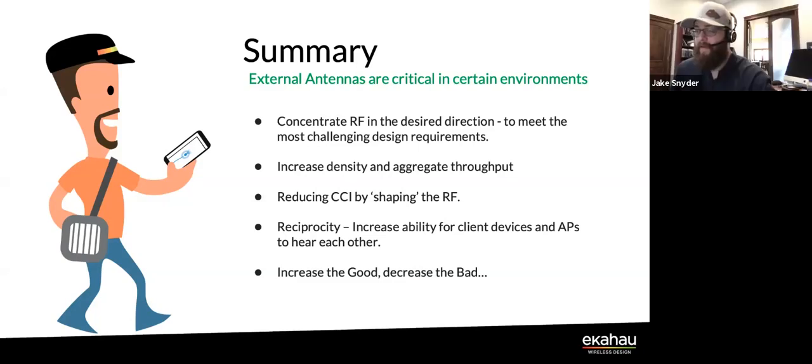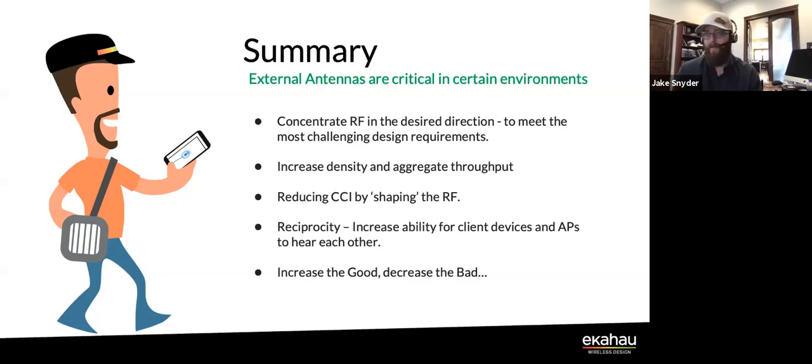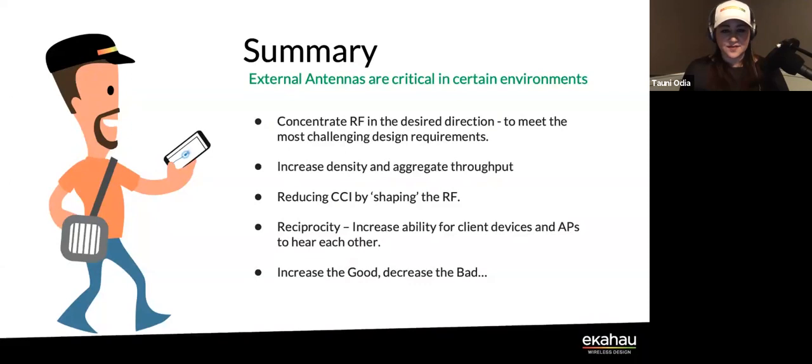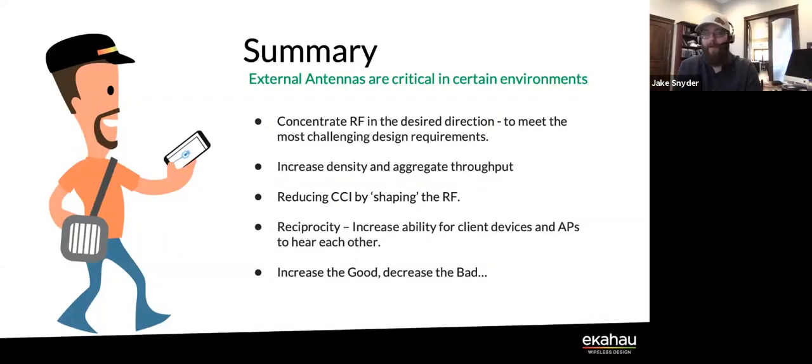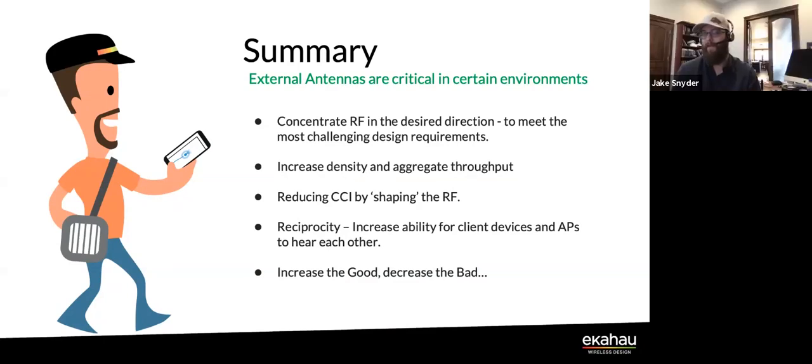I'll be honest, I think I'm going to jump in. I think validation is important. I can't tell you how many times I've walked in, and I have some pictures, where somebody deployed external antennas and they thought the little black rubber caps over the connectors were antennas. Or I had a coworker who ordered the wrong pigtails. The APs were RP-TNC and the connectors were N, and they just pushed the connector up over it and Velcroed it in place. That doesn't really do it. More pieces means more things to go wrong, so validating becomes exceptionally important.